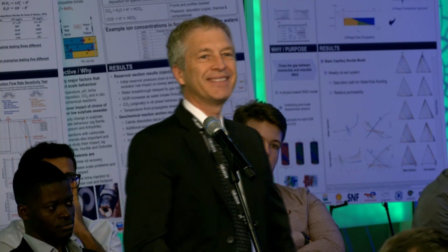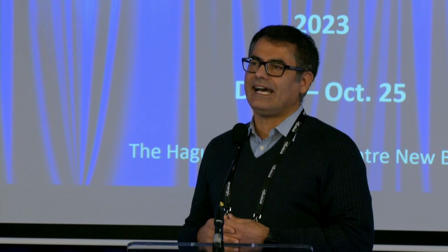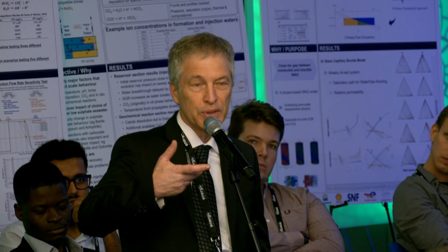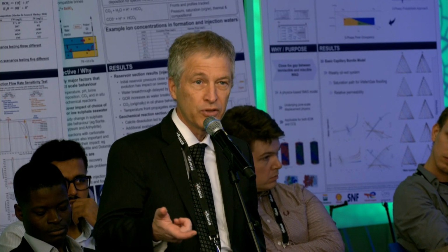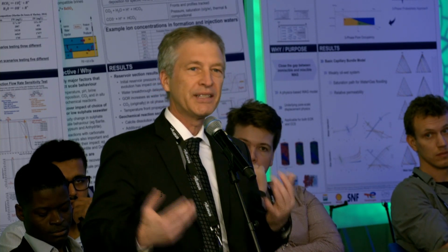I think you have to be careful with removing points, because for points that are there, you have already spent a simulation on them. They can be useful, and it's good to keep them if they are not misleading the proxy model. That can be checked in an effective way by including and excluding that data to see what kind of response you get, using validation approaches. We are also trying to do the opposite: not to use the proxies to find the answer, but to discard the worst regions in the search space. So that's another policy.